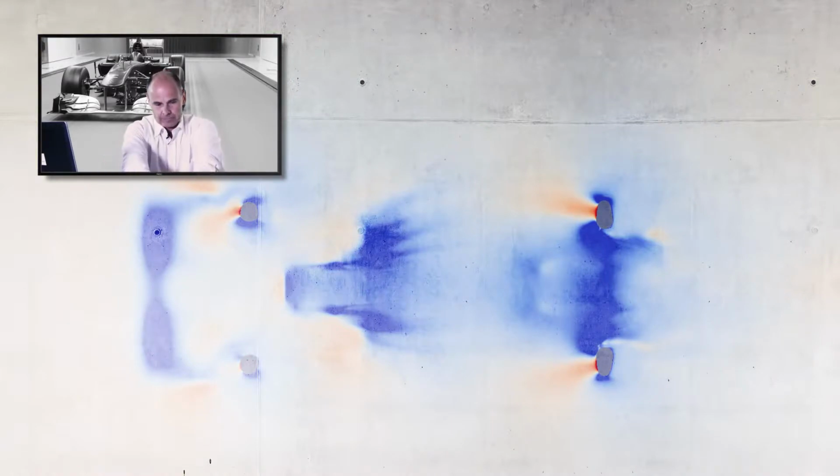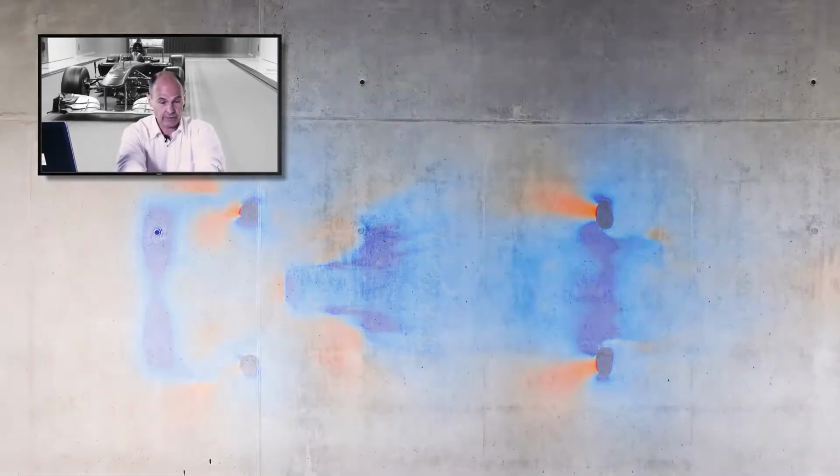But we still had the problem that we're generating a great deal of heat underneath the belt surface, which would limit it. So we went from a belt life of, say, 200 hours to a belt life of 50 hours when we put suction on. So then we decided to go for cooling. So then you take your metal bed for your moving ground system and you start to drill holes.